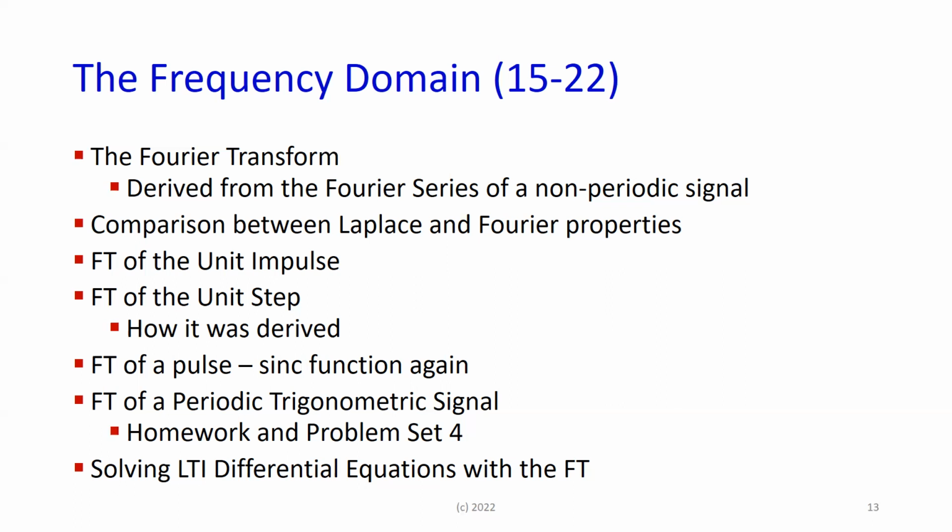The look of the Fourier transform, the version that we saw, was for all intents and purposes the same thing as the Laplace transform. For the Laplace transform, we integrate between 0 minus, just before 0, and infinity x(t) e to the minus st dt. For the Fourier transform, we integrate between minus infinity and infinity x(t) e to the minus j omega t dt.